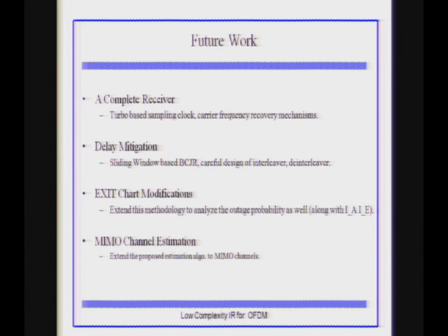The question is, what is big here? For you it's contradictory. You're claiming that the car is going very fast, so the channel changes fast. So if you go over 22 OFDM symbols, you should have enough ergodicity there to get an averaging out of it. You really tackle fast fading. Right, but you did go to 22 OFDM symbols, right? That's a lot for fast fading. The concept of outage is more for very slow fading, where the blocks are slower. It comes back to your delay question.